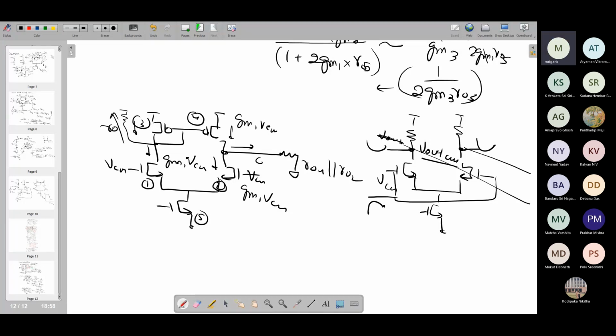But in this case, we don't have that happening. The signal is actually taken single-endedly. Therefore, as compared to fully differential output, this is in real sense worse, because in fully differential you were able to cancel out if you're taking the signal differentially. In this case, you are forced to take only a single-ended output, and therefore, if you look at the signal behavior, this is actually a finite common mode gain that you are getting as compared to the fully differential case. So that also we should keep in mind.